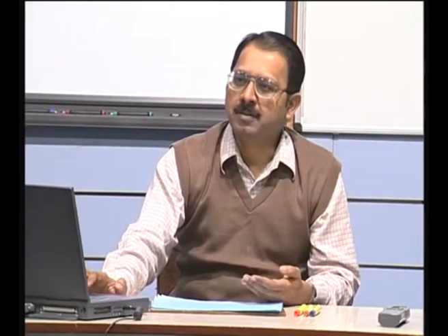In fact, your question is whether FMS and CIM are different or one is a subset of the other. I would put FMS as a subset of CIM, because in a flexible manufacturing system you are actually looking at the manufacturing process and the manufacturing system aspects and trying to integrate them. But CIM is broader, where you are also trying to bring in the business functions, which are not a part of any FMS. So, you can say FMS is a subset of computer integrated manufacturing, because in FMS you usually do not have business functions integrated, whereas in CIM you have this kind of integration.